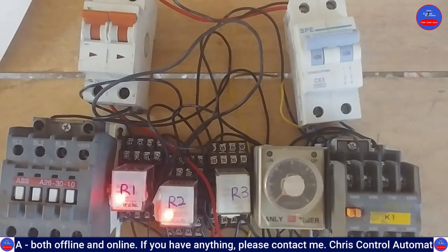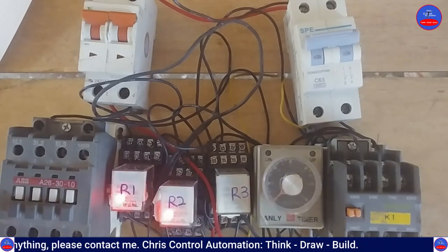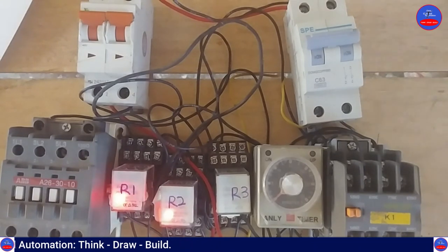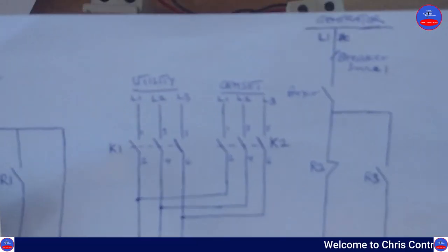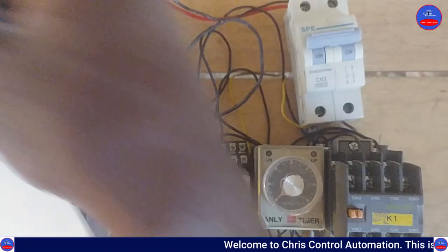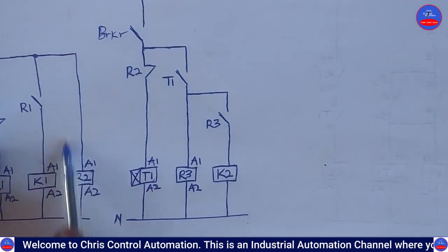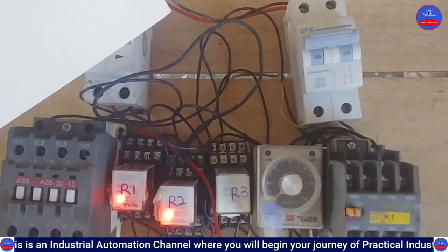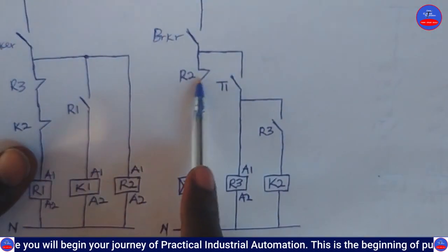Now let me tell you something here. What I told you earlier, the reason why I brought a timer, let's see the explanation here. Let's assume that our genset engine is still running, but the output of the generator is not off. As the utility power came, this one energized and it's opened here. So these components are all off. That is why this side is off. The relay 3, timer, and then the contactor 2, they are all off because this side is open.